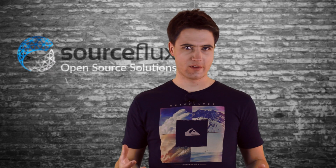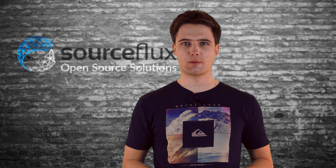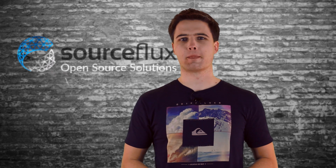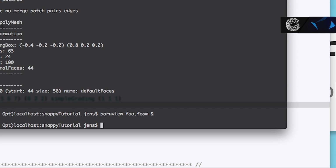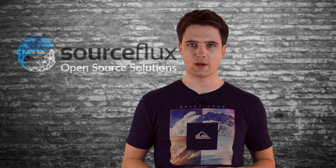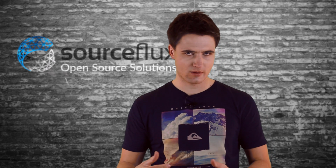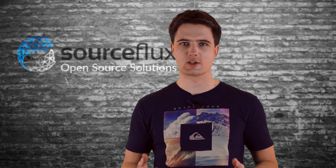In order to perform this check, please open either ParaView or paraFoam or whatever post-processing application you're usually using. I'm always using ParaView with a native OpenFOAM reader. This reader has the requirement though that there is a file present in the OpenFOAM case directory that you're trying to open, which ends on .foam with small letters. This file is of course not present in the motorbike tutorial case that we have copied, and I have to create it. I always create those files using the touch command.